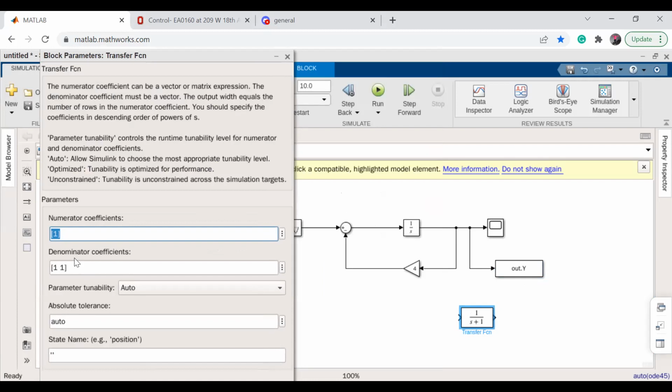But put the transfer function of your plant separately from your controller. Don't mix them together, because your controller has a K that you will change. Yes. You can, because then you just have to connect it to your workspace, like read vector A or vector, for example. Let me see what version you have.